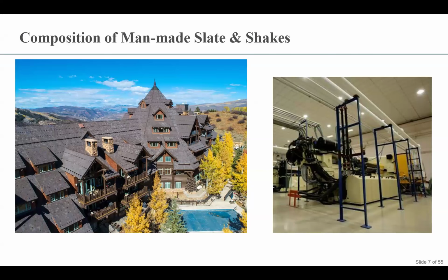Although each manufacturer has its own formula, composites are typically comprised of a variety of engineered polymers, rubbers, natural or cement components with fiber or polymer bonds. Using advanced injection and compression molding techniques, high quality composite materials are manufactured using engineered polymers consisting of UV inhibitors, color stabilizers, and fire retardants. There are many different types of polymers, therefore each composite is unique in its composition. Some manufacturers also choose to use recycled materials, and some choose not to.